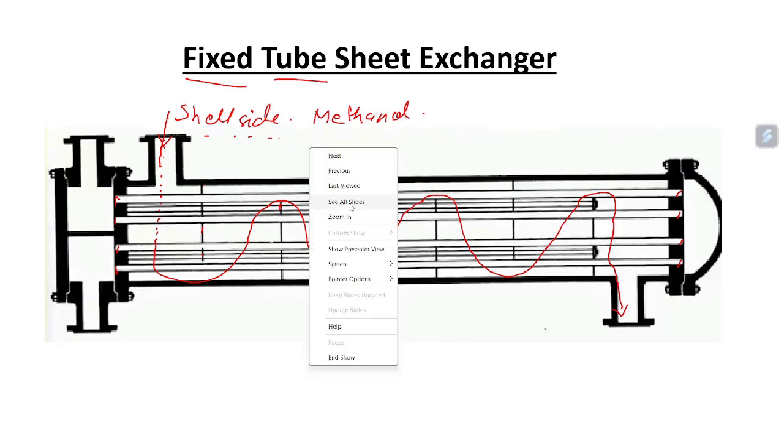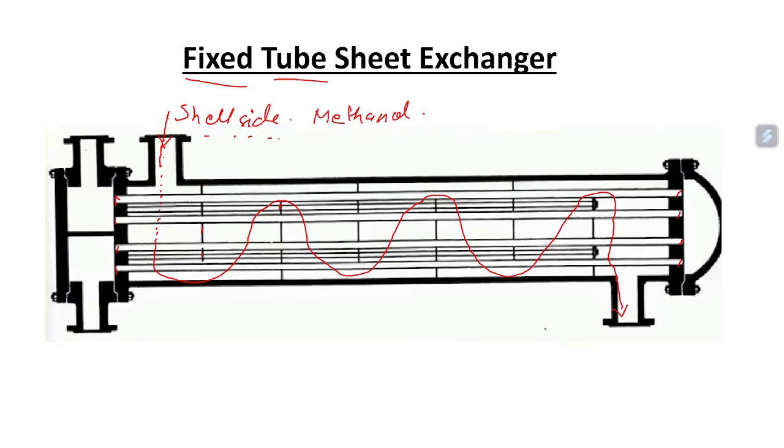Now the other thing is we have a tube side liquid. So let me just change the color first. So this is the tube side liquid. It comes from here, and you can see there is a wall in between. If you remove this wall, the fluid will get directly down from here, and that's the reason the wall is given. And there is another reason for this wall, I will tell you later, but for this purpose, the liquid, our cold liquid which is water, will come here.